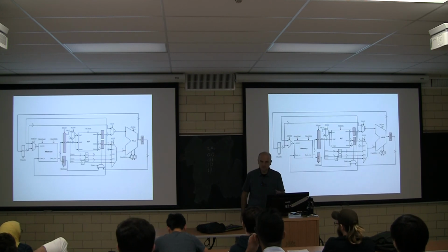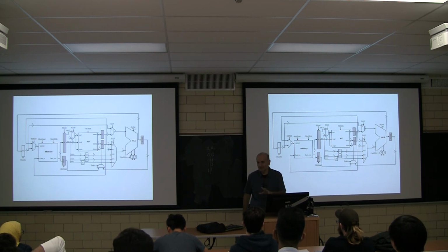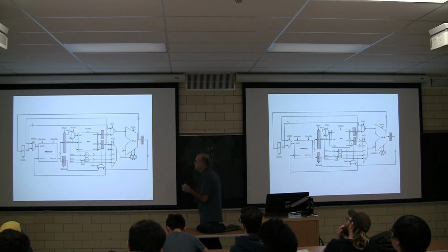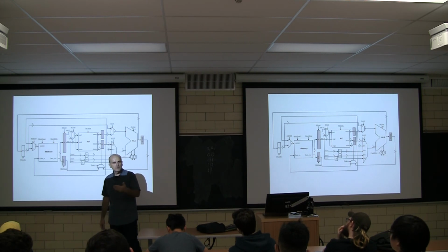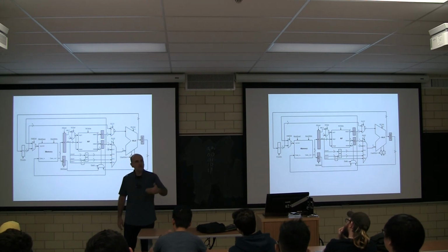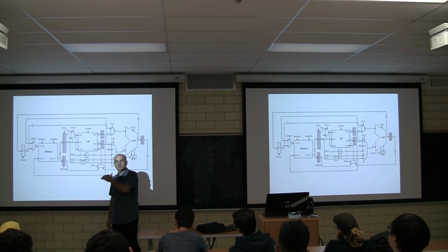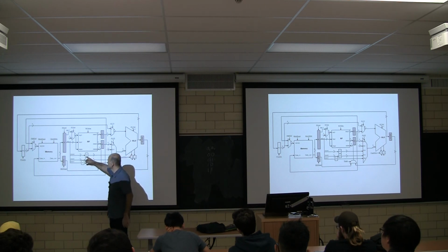Almost done. After this day, believe it or not, mark my words, you can build any CPU out there. Doesn't mean it's going to be the best CPU implementation, but you can build anything with this style. So let's do branch 0. Branch 0 says, if the 0 flag is true, then change the PC to be PC plus 1 plus the sign extended immediate 4. This guy. Okay.